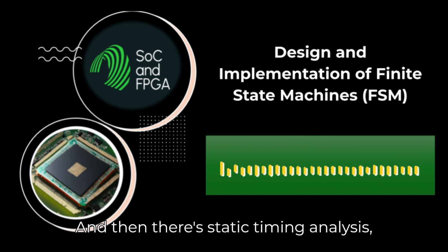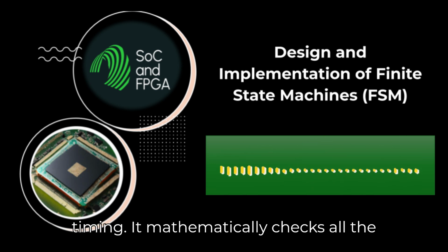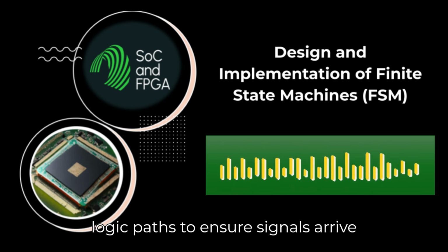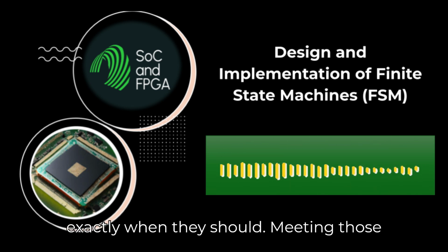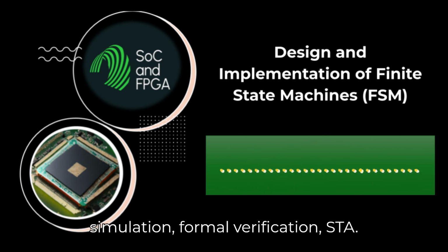And then there's static timing analysis, or STA. This specifically focuses on the timing. It mathematically checks all the signal propagation delays through the logic paths to ensure signals arrive exactly when they should, meeting those critical setup and hold times we'll talk more about later. Okay, so we have simulation, formal verification, STA.